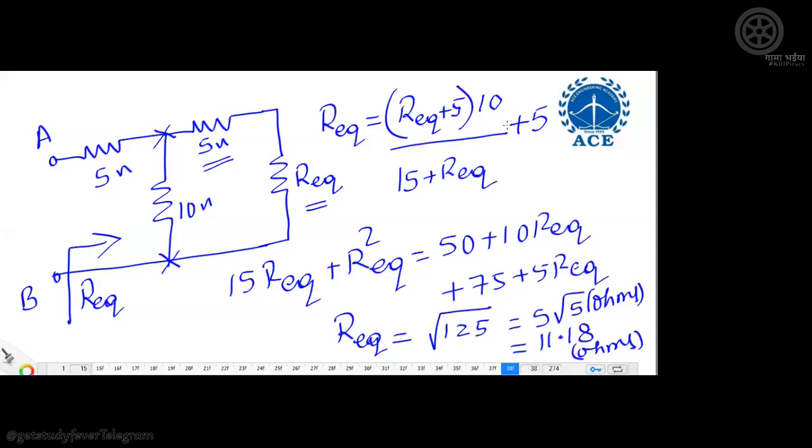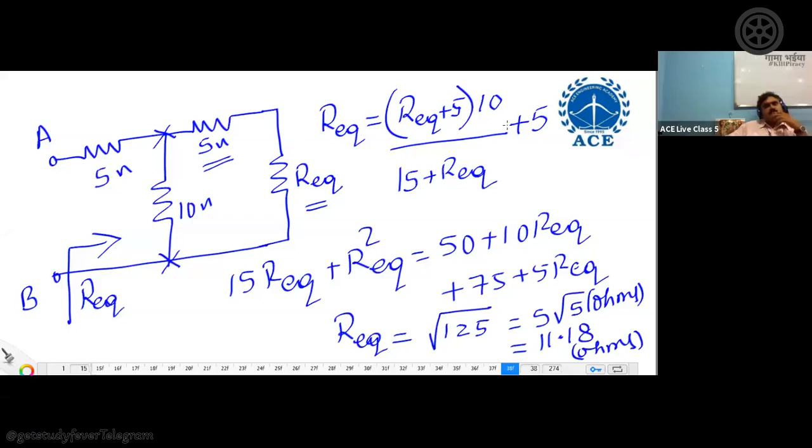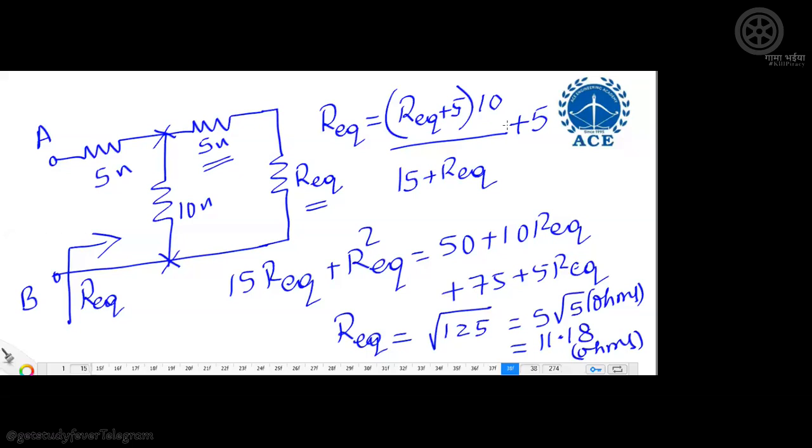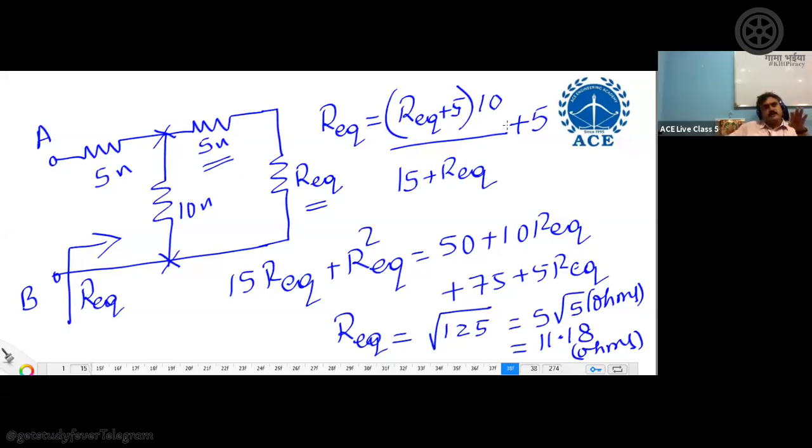So after settling state that I got, but when we have to calculate settling time, then we don't take the current source, because there is no current source. There is no initial value of the current on the inductor at that time. When you are immediately switching at 0 plus, there is no stored value of the current, so you need not show anything. That current will come after steady state has been reached and you again open the switch to remove your source. Then that will come.